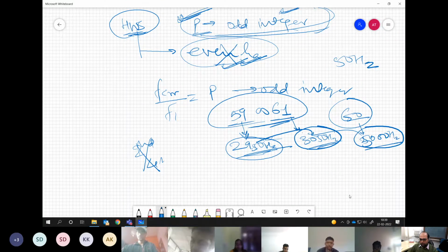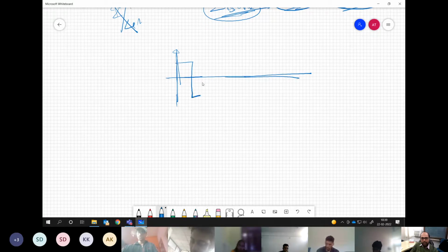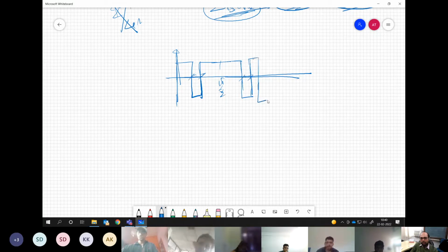Now we have seen for low switching frequency that once we maintain these two things, then the rest of the things are basically maintained by our switching angles themselves. So whatever switching angles alpha 1, alpha 2 we are having in one quarter cycle, we will maintain the other quarters with respect to this, in order to have quarter wave symmetry and then three phase symmetry. We will keep the angles in that manner.